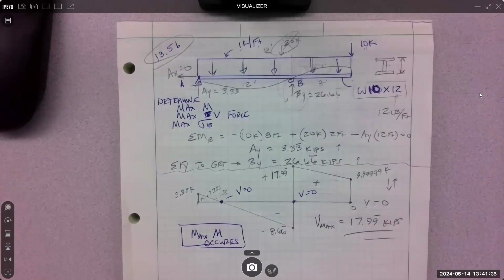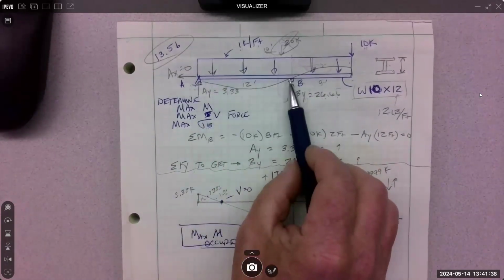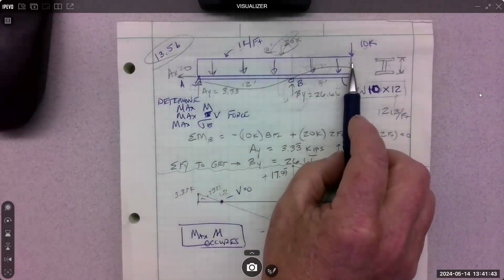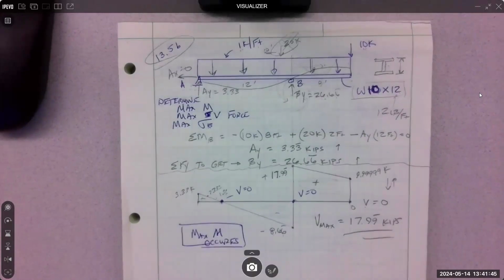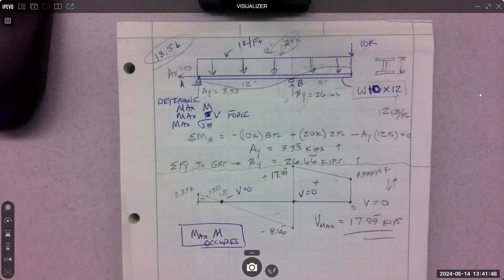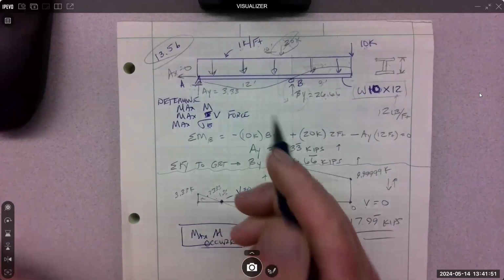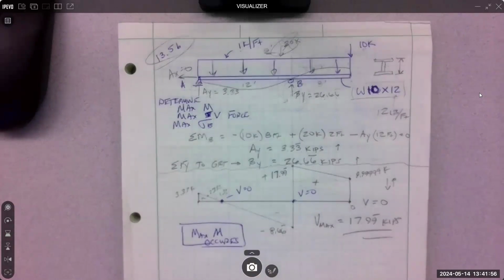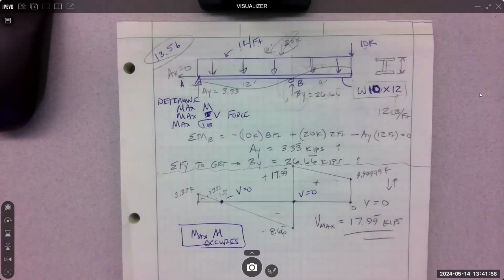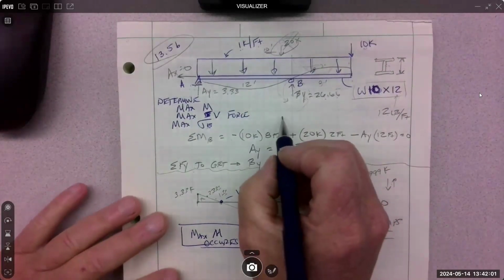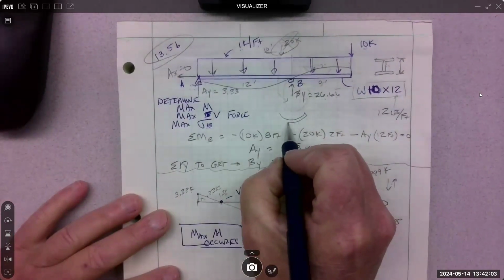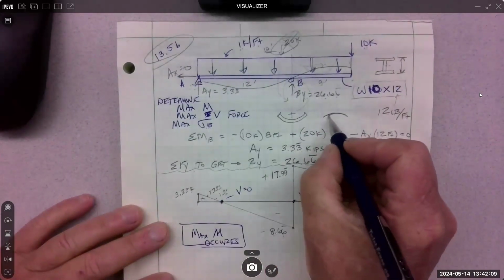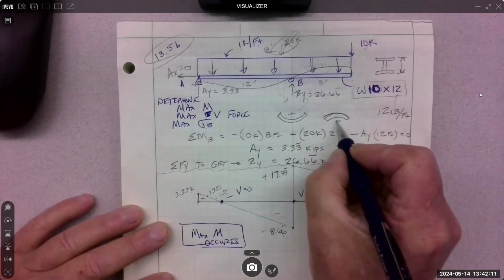Right? So we got concavity here, because there is a solid 12K in here for sure. And then there's 10K out here. You always just dramatize it. It's going to look much different than this, but approximately like this, right? You can visualize. Yeah, it really helps because a beam that has concavity up, that's a positive moment. So a beam that deflects like this, and again, I'm exaggerating it, that is a plus moment, and a beam that deflects like this, that is a negative moment.